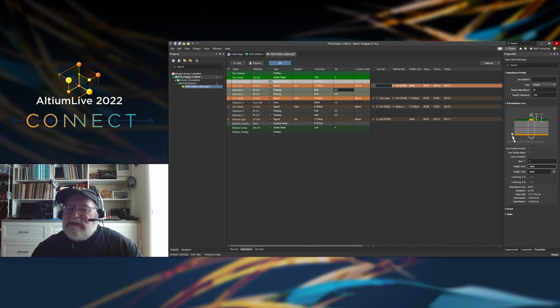We had some of these fringe field lines that are going between the signal and the return. Most of the field lines are going this way, but some of them are going this way. So where we had air before, we're going to add a higher dielectric constant. We're going to increase the capacitance a little bit. That's going to pull the impedance down.